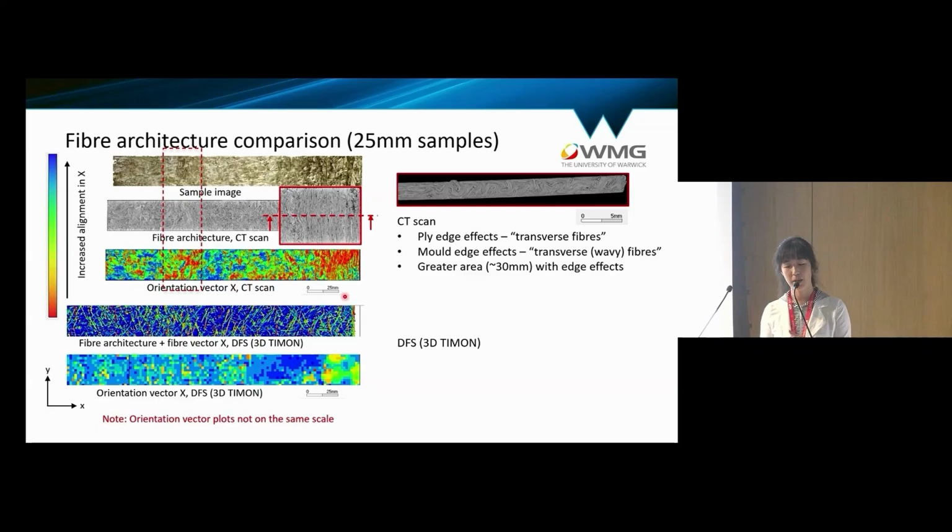So when your fibers crash into the mold wall, that shock wave then gets propagated along the material. So you get a large area of material that's affected by this edge effect. And that's actually very critical for SMC parts because the majority of these components are molded net shape, so there's no trimming afterwards. So you get this edge effect all along your component.